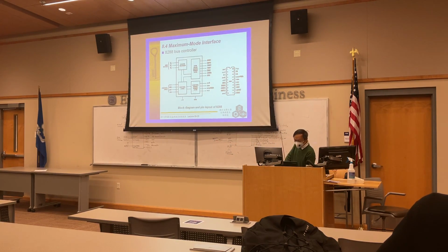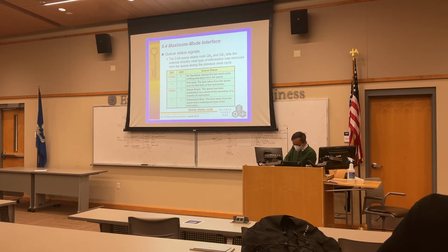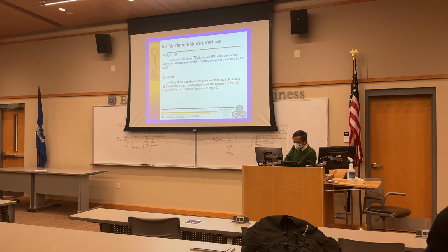Okay, now let's break it down. This is actually the bus controller, the lock signal, and the queue status. Queue status 00, no operation. 01, first byte. 10, the queue is empty, and 11 is a subsequent byte. Okay, this is actually for the queue status.